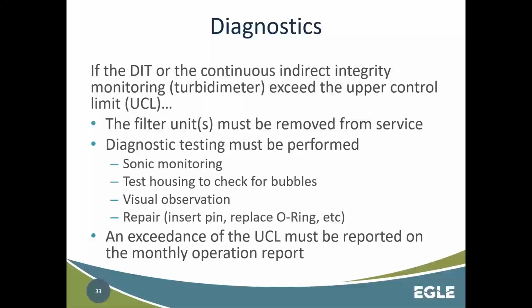A lot of the operators at well-run membrane plants that I've talked to, in addition to their direct integrity tests, also do their own, they call it an integrity verification program. So they will periodically do sonic testing, and it's a glorified stethoscope that they stick on each of these modules.